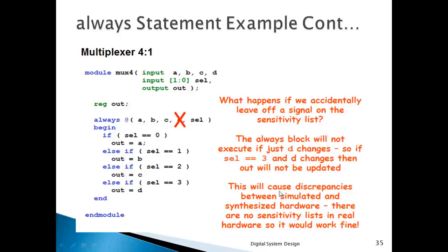This will cause discrepancies between simulated and synthesized hardware. There are no sensitivity lists in real hardware, so it would work correctly from the hardware perspective, but from the simulation perspective, out is not updated with this value if D is not included here.